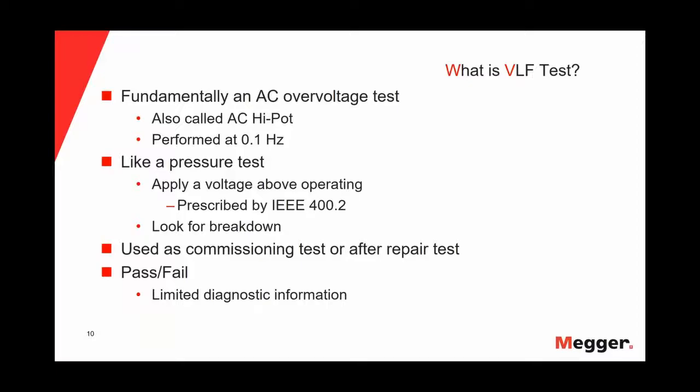In the VLF test, some standards allow you to decrease the frequency. Some other standards don't allow that, okay? But normally, we will say that the official frequency for the VLF test is 0.1 Hertz. And the VLF test is pretty much like a pressure test. We will apply a voltage above operating. The voltage will be prescribed by a standard, for instance, the IEEE 400.2, and we will look for a breakdown.